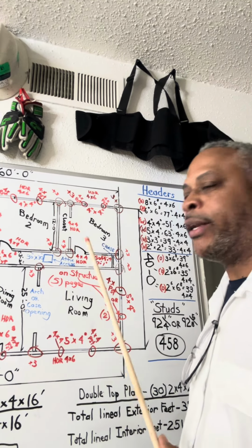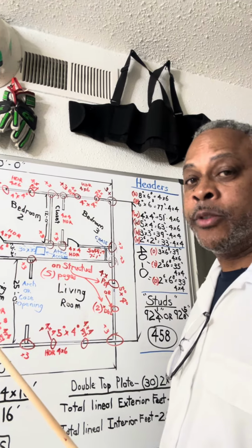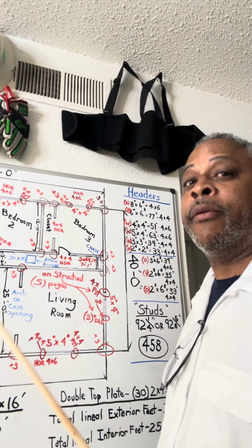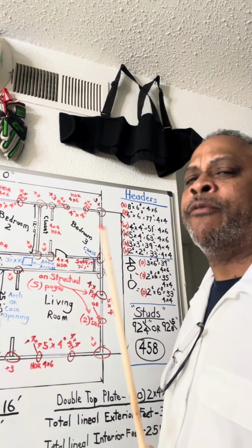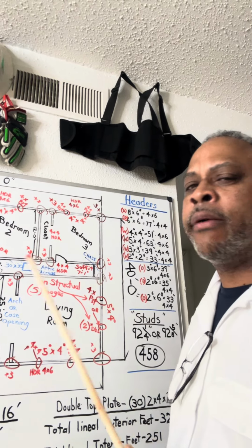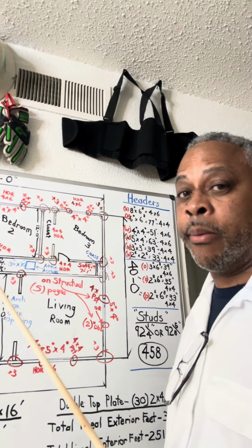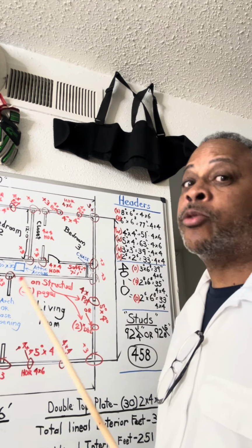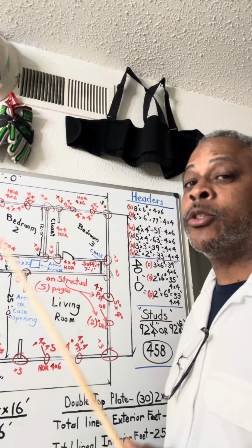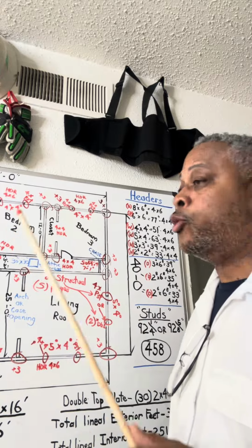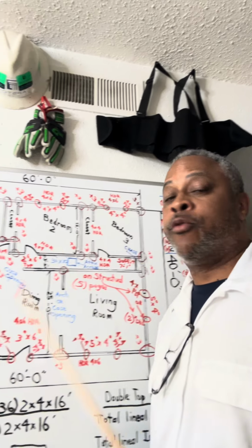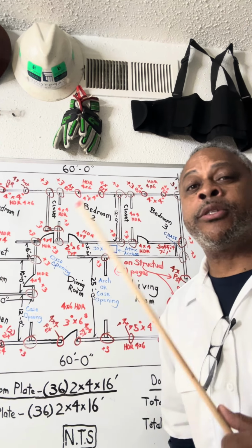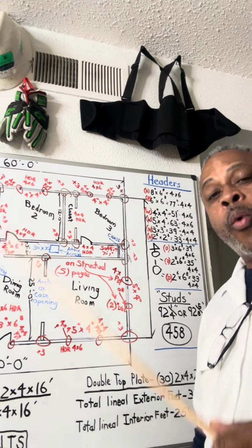Don't do that. I need you to keep lumber on this job, because you're going to go through lumber, and framers do waste a lot of lumber. If you do it the way I'm telling you, you will never have a problem going short on lumber. And you will not have a lot of lumber left over because, believe you me, professional carpenters know how to use scrap lumber. Do not throw anything under 4 foot away. Scrap is considered 2 foot and less, 1 foot.